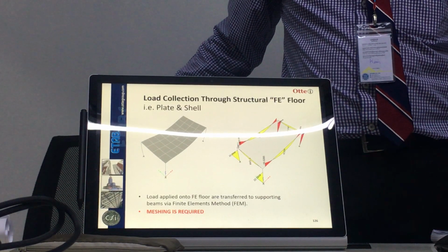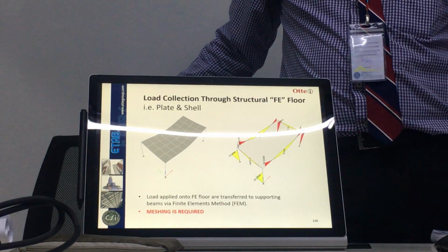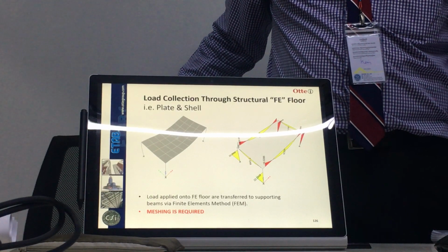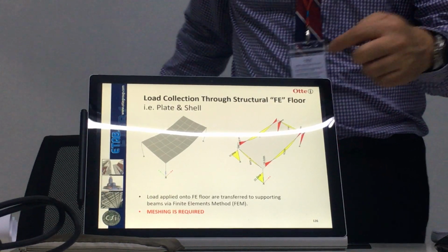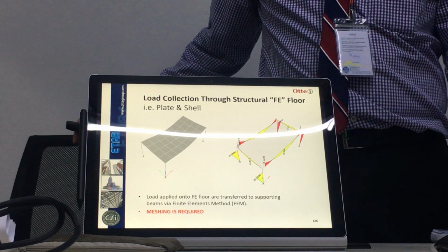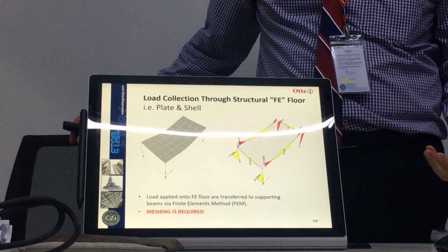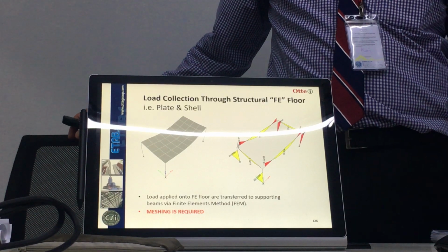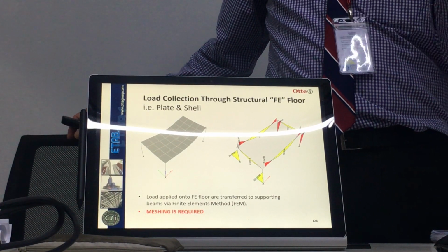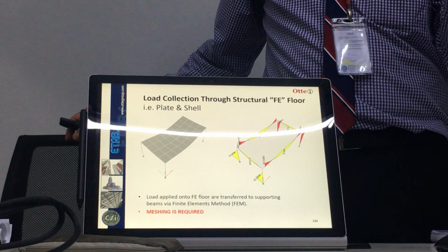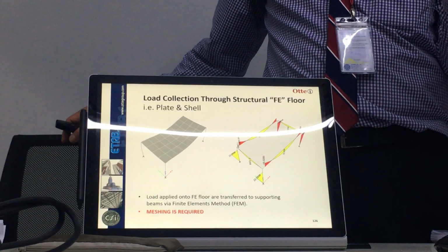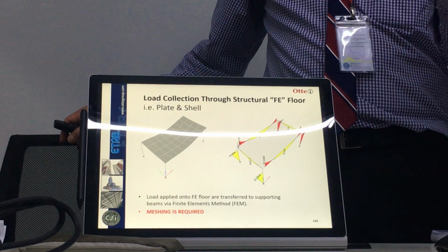And how do you know 4 is enough? Your goal is to find the bending moment of the beam, right? You see what I mean? So use 4 elements, check what the bending moment is. From 4 elements, you change it to 6 elements. Does it change a lot? If it doesn't change a lot, it means the 4 elements is good enough. Like for example, from 2 to 4, right? 2 changed to 4, bending moment changes a lot. So 2 is not enough, 4 is good, right? Now 4 changed to 8, bending moment doesn't change much.